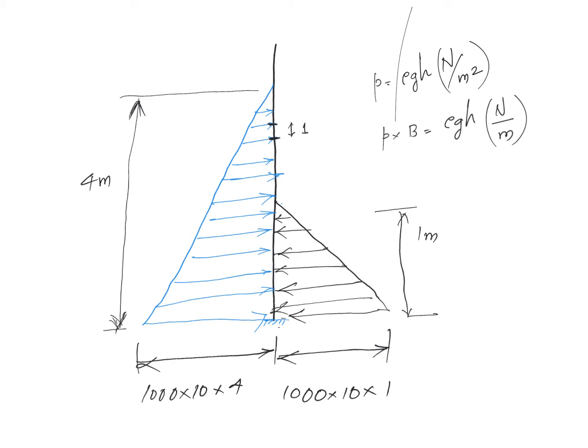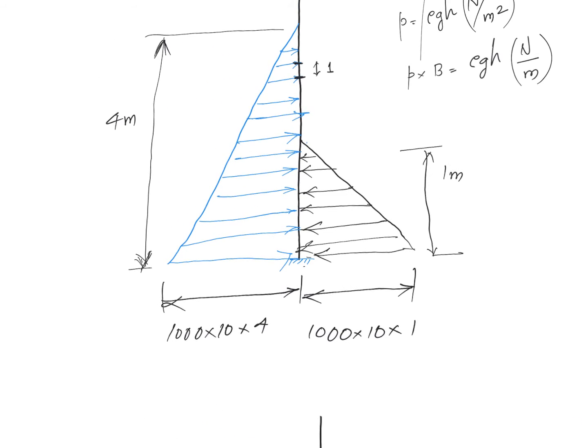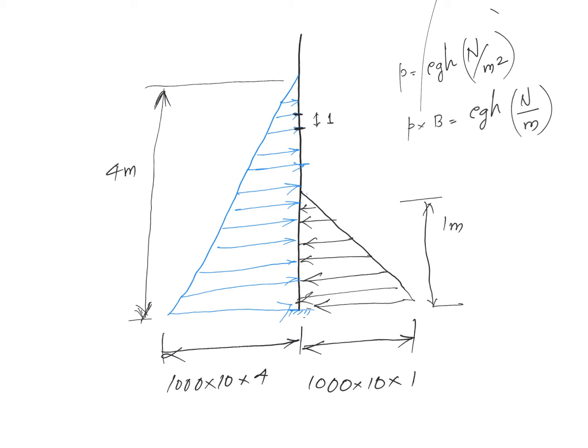Now the next thing is, to compute the bending moment, we can work with statically equivalent loads as well. So we need to compute the statically equivalent load for these two loading profiles, which is also not very difficult. We know this varies as a triangle, so the equivalent load will be equal to the area of this loading profile, which is half times height times base length.